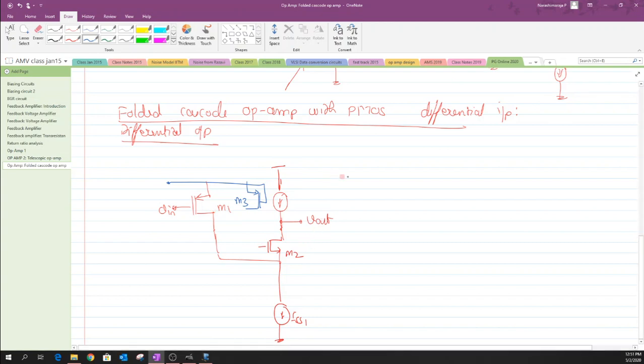And now I will also try to mimic this similar structure, the load structure, and let me tap this output so that I can have a differential output configuration here. Let me also have our cascode device added along with it, and let us fix this voltage with some sort of DC potential VB. Again, this has to be supplied with a tail current which is labeled as ISS1 itself. Okay, so let me label this one as I1 and this one also as I1.